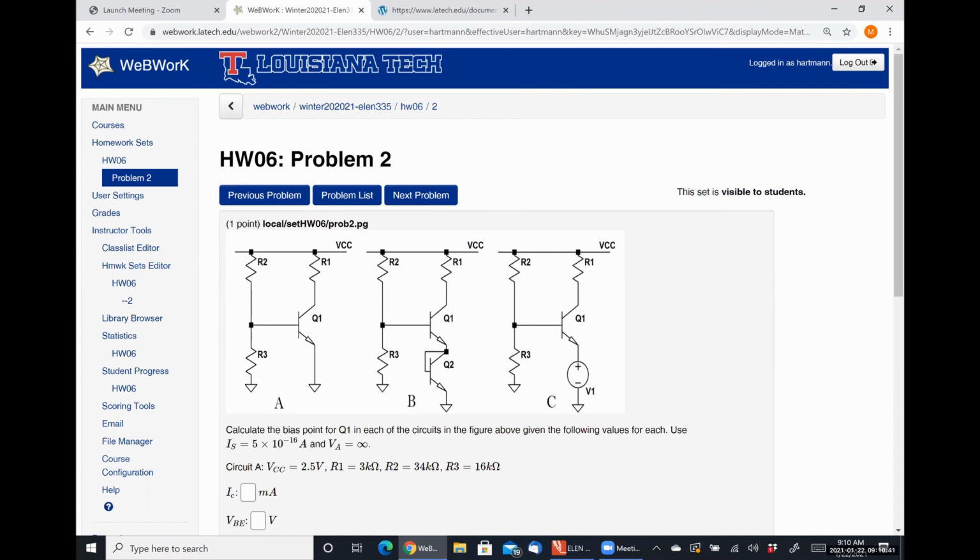The reason I say they may not be exactly the same is because on this guy, there's no resistor. The emitter current is going to split up and then come back together. So just recognize that Q2 is in series with Q1, and that's going to make your life much easier. I think you could probably model it as a simple resistance. Based on that knowledge would be an easier way to approach it.